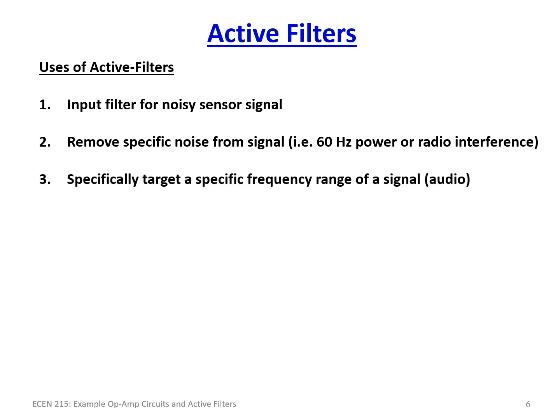In this case, you could be specifically targeting a frequency range. As we were talking about in the frequency response lecture, you have different frequencies of interest, for instance electrocardiograms, audio frequencies, things like that. Or you're specifically looking for a radio frequency. And so you would specifically target a frequency range and build, in that case, a band pass filter, which will only allow the frequency signals of interest that you want.